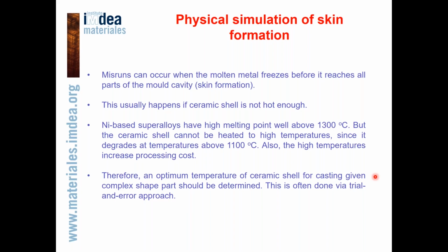Therefore, we need to determine an optimum temperature of the ceramic shell for casting a given complex shape part, which would allow us to avoid misruns. This is often done by a trial and error approach, which consumes a lot of resources.